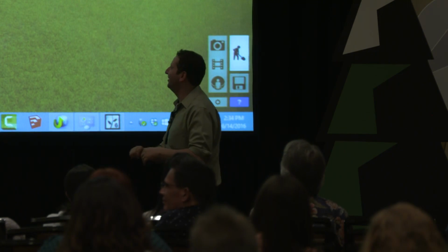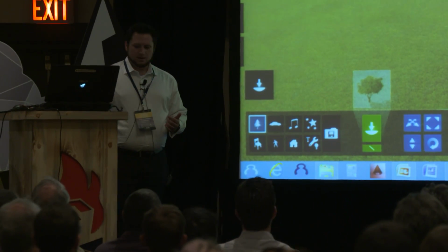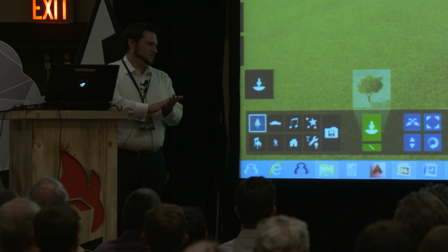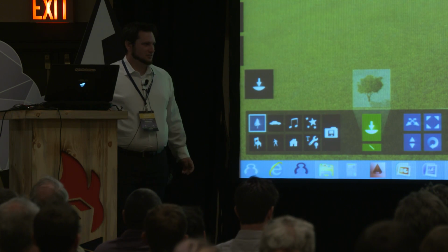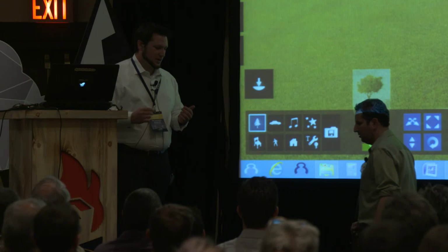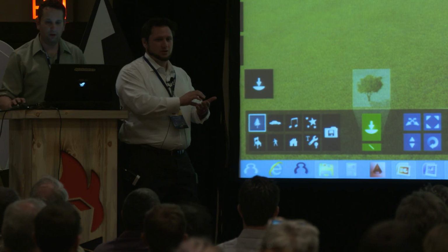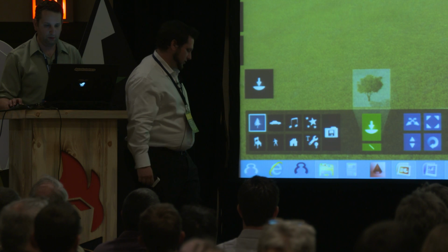One cheap and easy fix, if you're just using it to work on details and it's not a view you're trying to export, is the Z key, which activates the field of view in SketchUp. You can lower that to 1 or 5, and it's going to look weird because it's really close to parallel projection. But if you're just working in detail, it'll let you get a lot closer in without hitting the clipping plane as quickly.